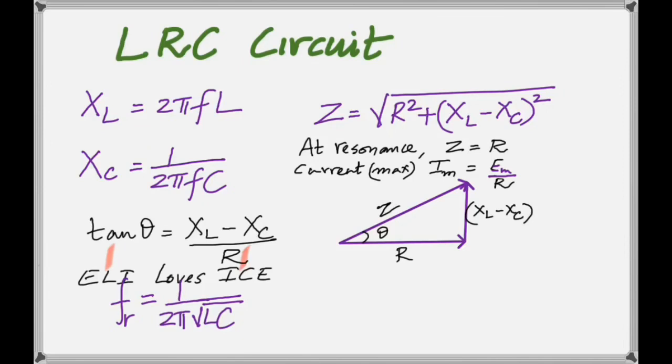So let's say in a problem you have 120 volt, blah, blah. That 120 volt is the RMS voltage. So by default, what's given is always the RMS voltage. Note that down. Many times I tell you it's the RMS, but I need not. By default, it's always the RMS. If it's the peak, it'll be mentioned. Okay.